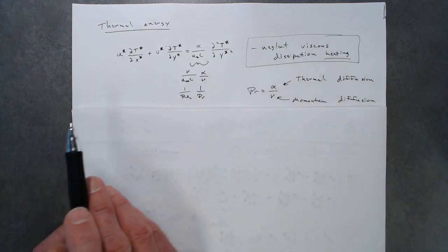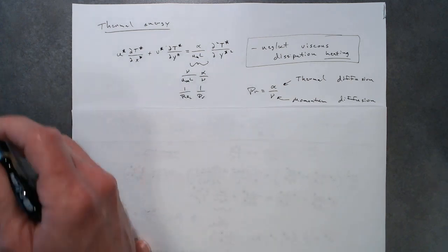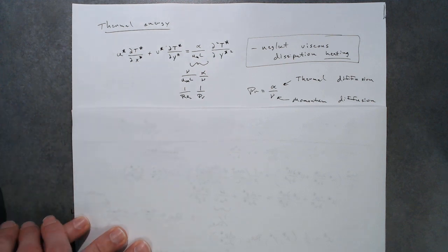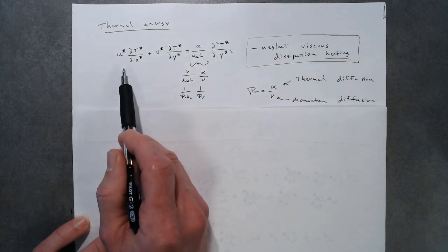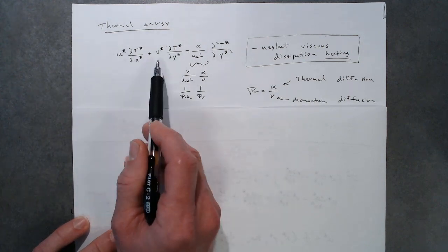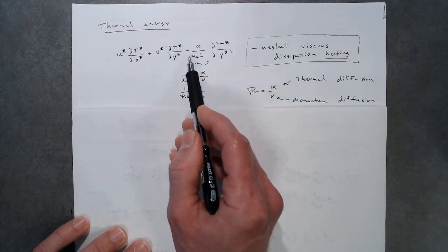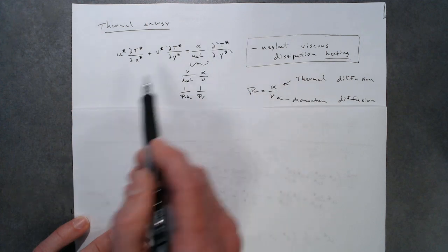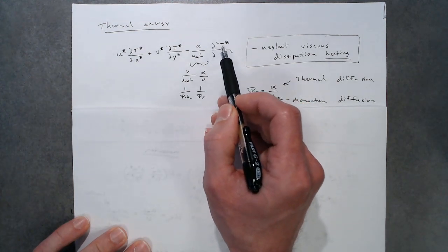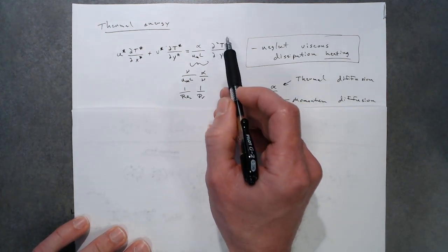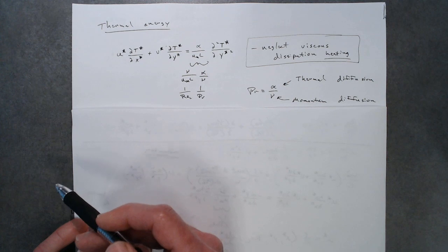If we do that, then we end up with a fairly simple equation that, again, looks pretty similar to the one we looked at before, without that pressure gradient term. We have this advection term, the rate at which fluid flow is carrying thermal energy into or out of a region of interest. And then we have this diffusive term, and you recognize this term immediately from the heat diffusion equation, that the second derivative of T with respect to position, in this case non-dimensionalized, tells me how quickly heat is diffusing into or out of my region of interest.